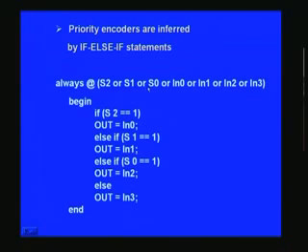So next thing we are going to see is, once again already covered, a priority encoder as such, and this is the always block which brings out the priority encoder. First, this is given the topmost priority. For example, you can regard it as a single 3-bit input, or rather as 3 different inputs. Here S stands for the select. So we have 3 selects here, and we have 4 inputs once again. It's also a mux basically, and you need to get either in0 or in1 and so on, depending upon S2, S1 or S0 in this fashion.